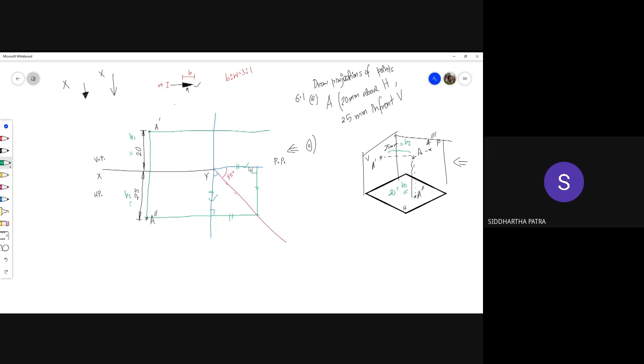So you want that point at this much distance from the vertical plane. So you can extend this line, and the point of intersection you can treat it as a triple prime, because over here, this distance, which is 20 millimeters, is a distance from the horizontal plane, that is this much above the horizontal plane, and this much in front of.